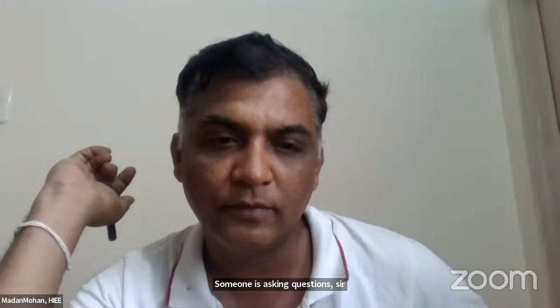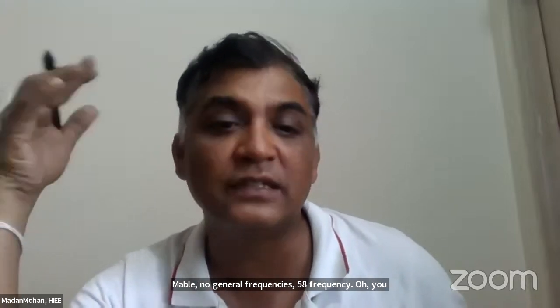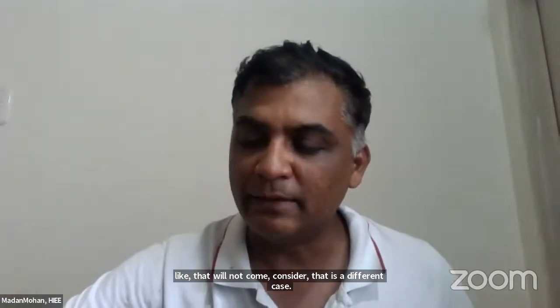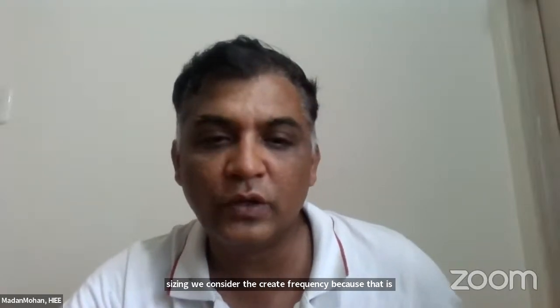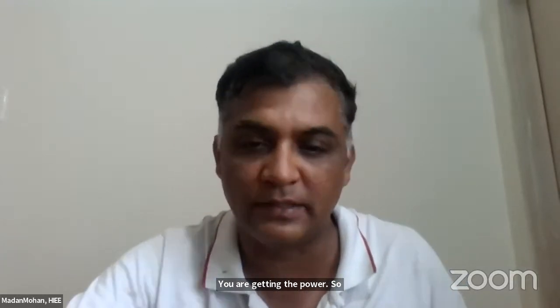Someone is asking a question, sir. There's a question from YouTube Live from Raj, saying: should we consider variable frequency in the derating factor here? No, generally our frequency is 50 hertz. That will not be considered; it is a different case, maybe what he is asking about. When it comes to cable sizing, we consider 50 hertz frequency, because that is the frequency at which you are getting the power. So variable frequency will not be considered as a derating factor for cable sizing.